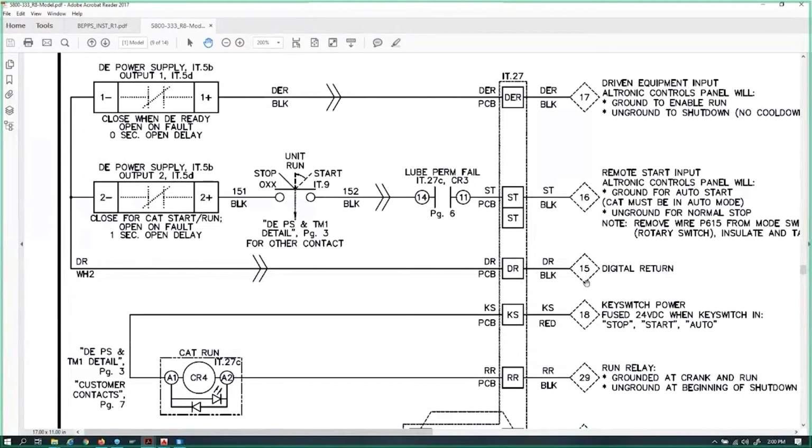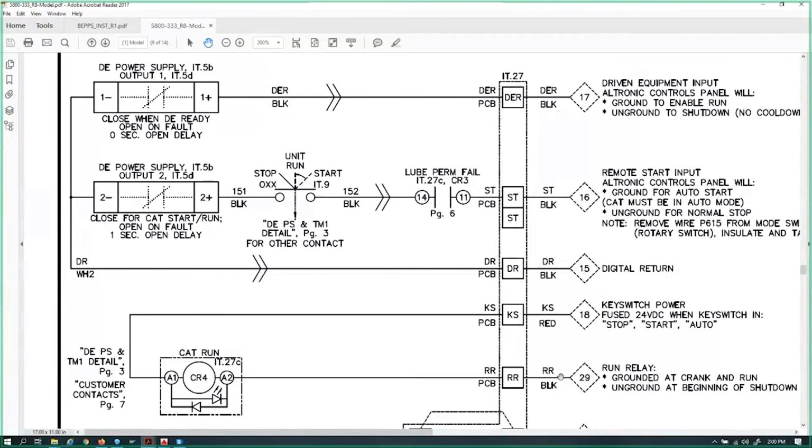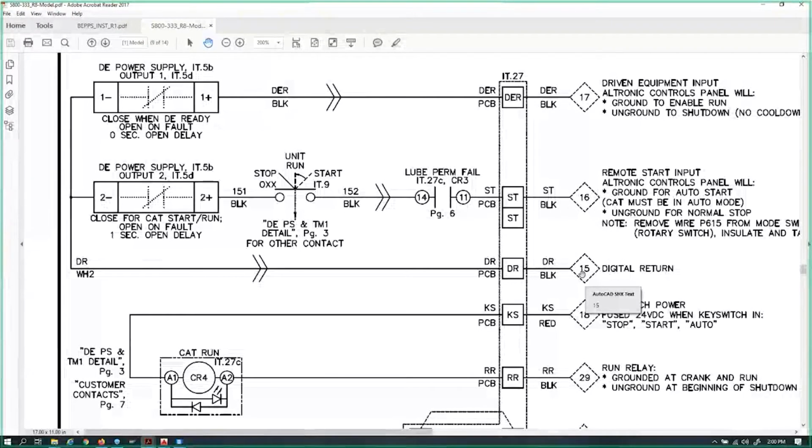So I can pick up a 103 anywhere in the panel, which is positive 24 volts coming into the panel. And I can do a test first. I can measure voltage between that 103 and any 102 in the panel, which we know is a ground. And I can verify, oh yeah, we got 24 volts. Well, if 15 is a good ground, then I should be able to go to that CAT terminal and put the black probe of my meter there while I'm leaving the red probe of my meter still back on a 103, and I'll get 24 volts if this is a good ground.